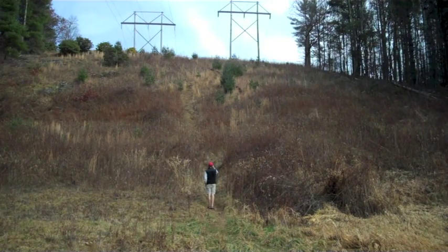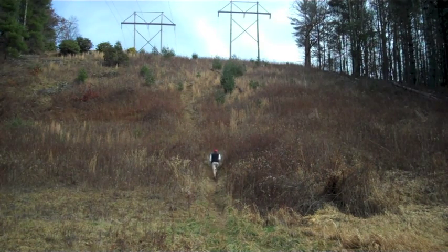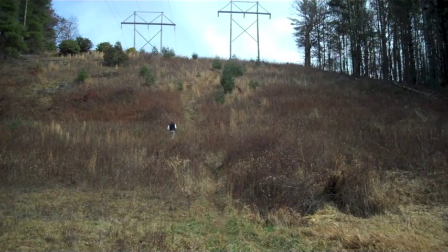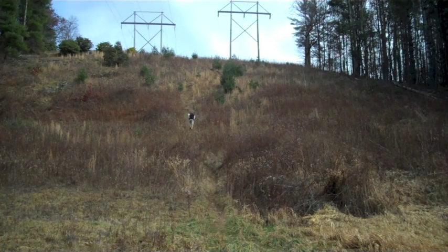The two most accurate methods of finding the elevation drop are direct height measurement and measuring water pressure. The method I'm demonstrating here is the direct height method, working uphill from where the turbine will be up to the intake. Normally, you would want an assistant up the hill from you, for their feet to act as a marker for the spot where the site level is actually level, but as you can see, I didn't have one at the time, so I picked a specific piece of dirt or rock to mark the spot instead.